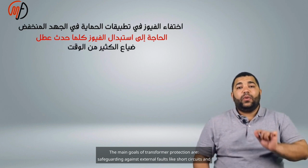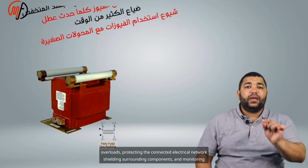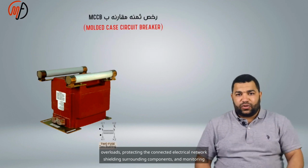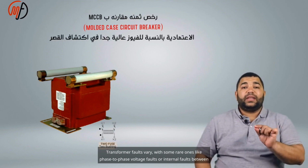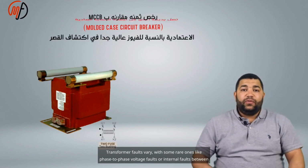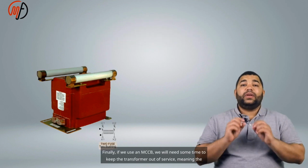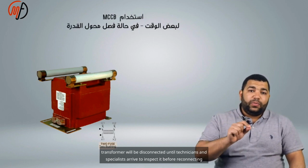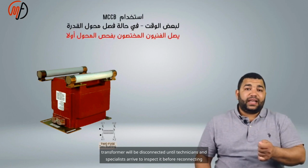The main goals of transformer protection are safeguarding against external faults like short circuits and overloads, protecting the connected electrical network, shielding surrounding components, and monitoring operations to minimize risks. Transformer faults vary, with some rare ones like phase-to-phase voltage faults or internal faults between windings, especially in low voltage applications. Finally, if we use an MCCB, we will need some time to keep the transformer out of service, meaning the transformer will be disconnected until technicians and specialists arrive to inspect it before reconnecting it again.